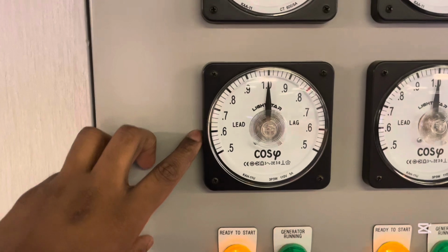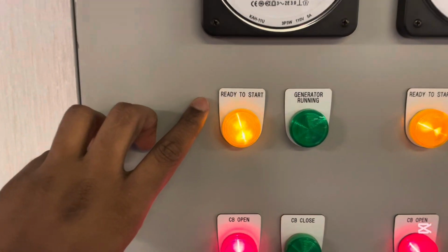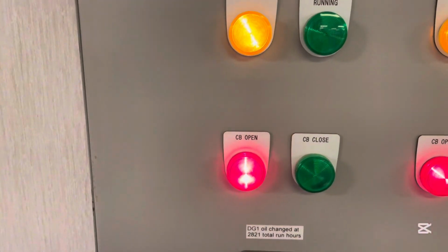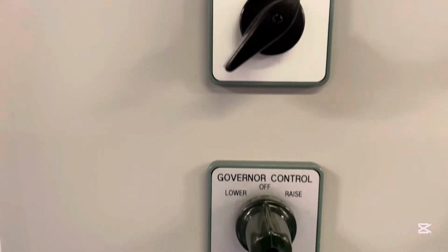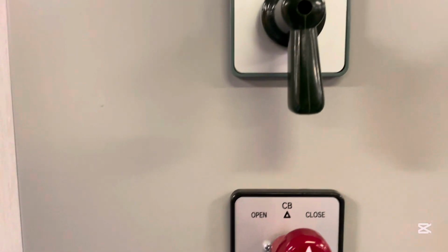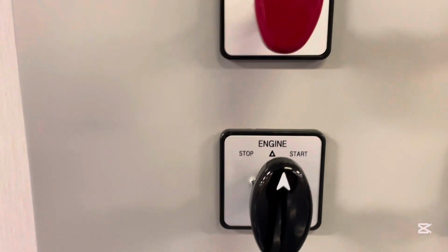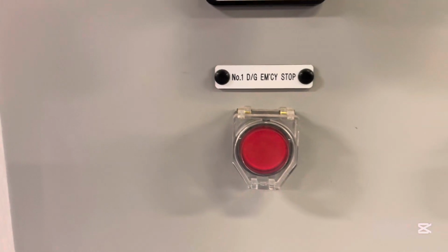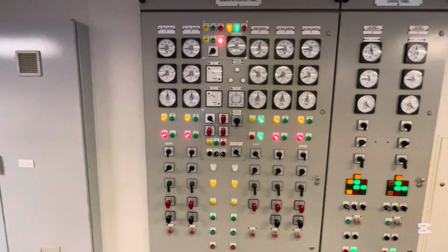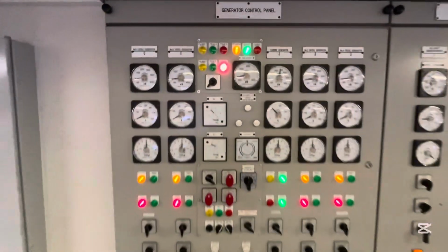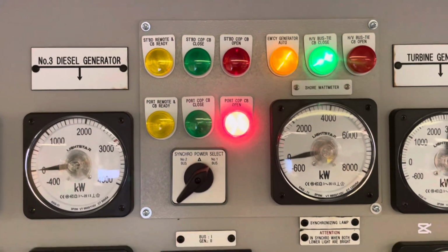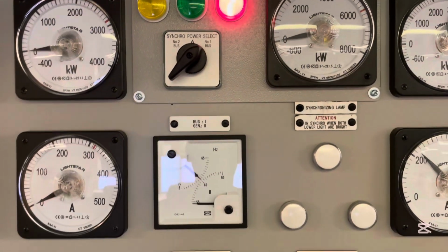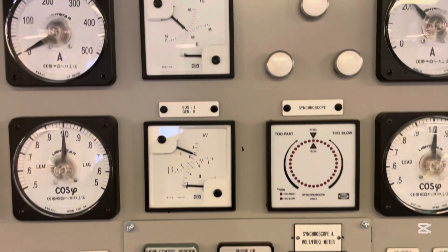All right. These are the meters and indications that are normally on a generator control panel. The ammeter and generator control position are for the generator, whereas the governor control, the one which controls the speed and starts and stops the engine, is basically controlling the engine. That is why I said this is an engine control panel as well as an alternator control panel. The engine and the alternator are coupled together. The engine is driving the alternator. The mechanical force is converted into electrical energy, the basic principle of an alternator or generator that we know.